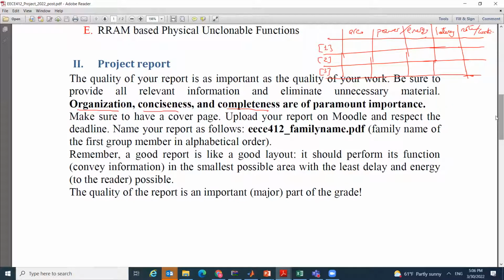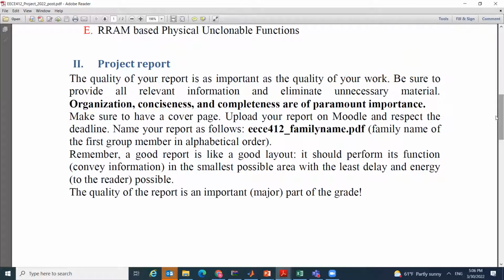In addition to this, it is good to try, for example, to go back to the basics that you know. For example, we know that an adder relies on XOR, or a tutorial that would tell us the basics, and so this they are defining. We know how to build the XOR in CMOS, but it is costly. It takes, for example, 8 transistors. Those guys are using the memristor and 3 transistors, and I will talk about this information next.